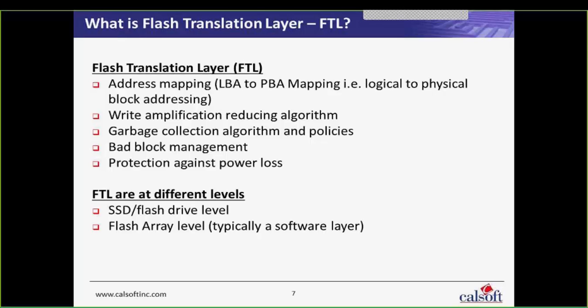So FTLs, again, as I said, can be implemented at different levels. Normally a couple of Flash vendors implement them at a Flash array level and at a controller level as software, or this again can be implemented at an SSD or a Flash drive level. So moving on to the next slide.